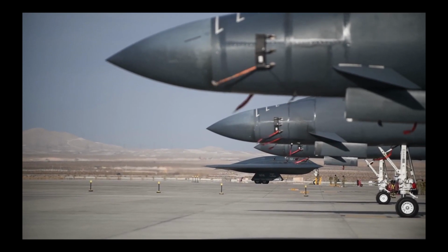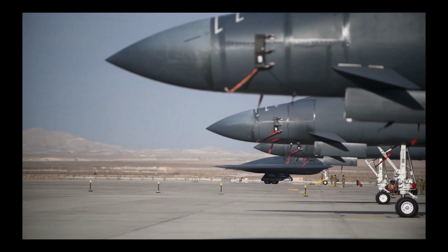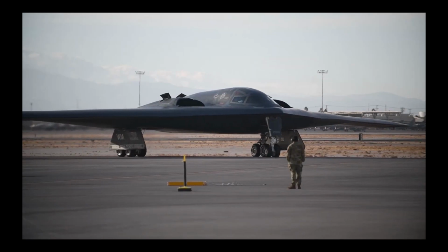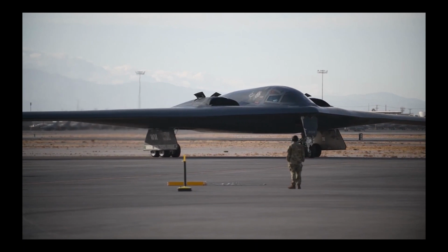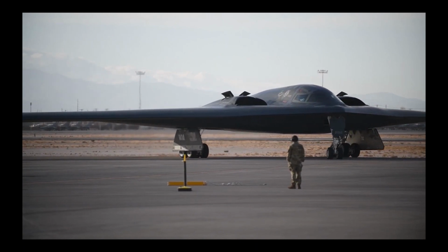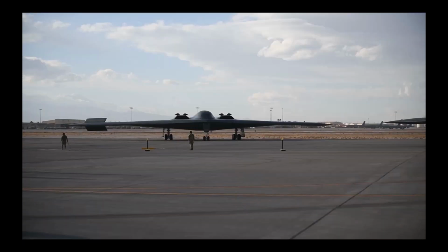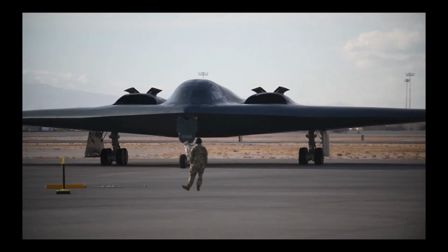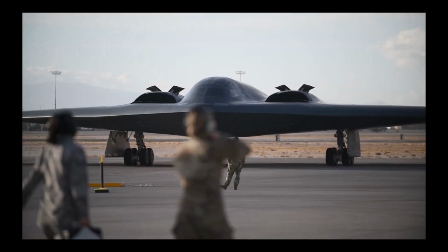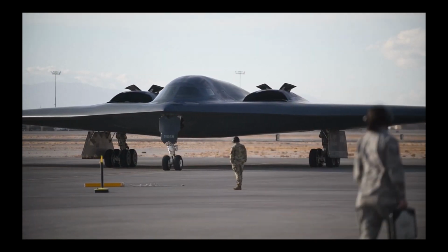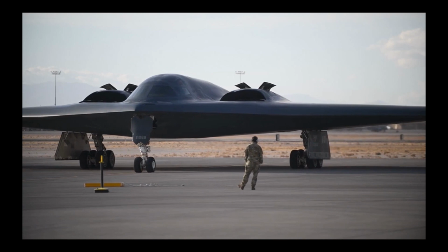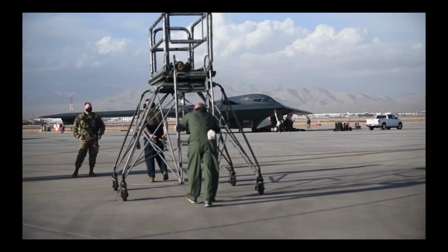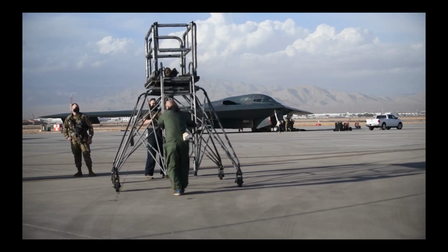In addition to wing bending and asymmetric load distribution, they also identified inadequate control surfaces on the trailing edges, which control both the pitch and roll of the aircraft. They found significant problems when the aircraft's pitch instability yielded an open loop time that necessitated immediate response from the control surfaces, needing much larger surfaces and a higher rate of actuation.